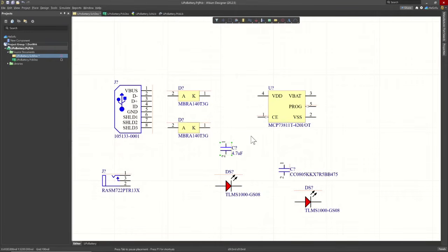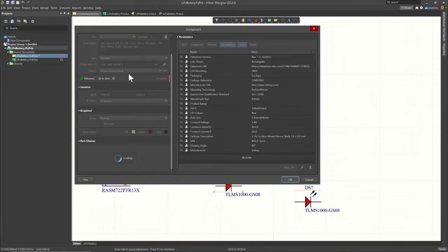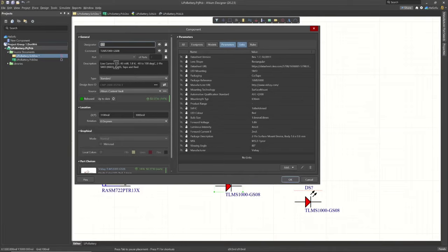And you can change this to whatever you like, really. And then the second one, just go ahead and delete that, and then copy the first one, and then with Control C and then Control V to paste. Likewise for the diode, you can double click on the diode body and then look at the information here. You could just call it a red.